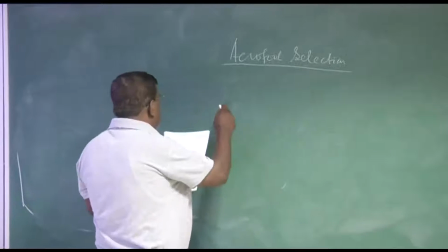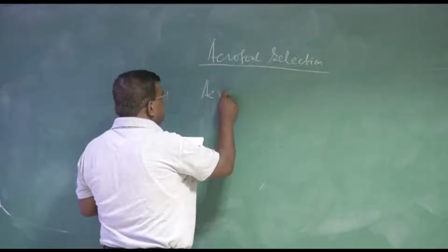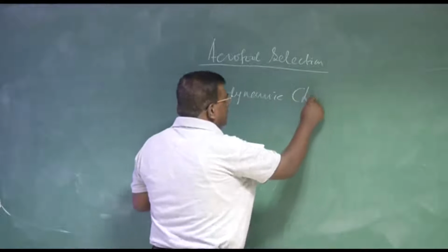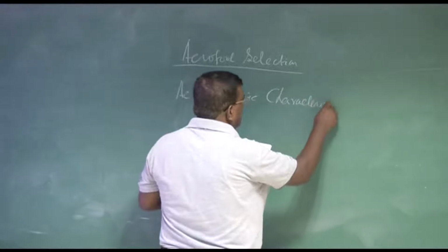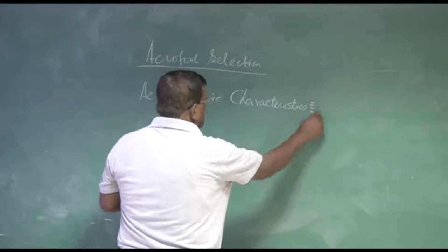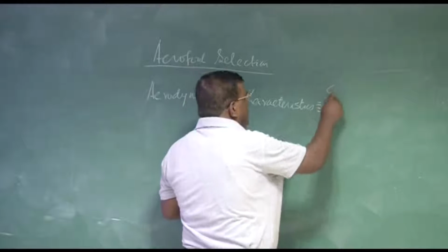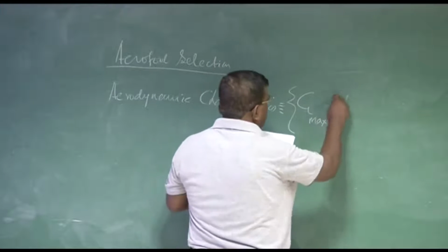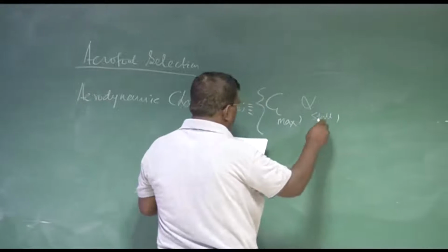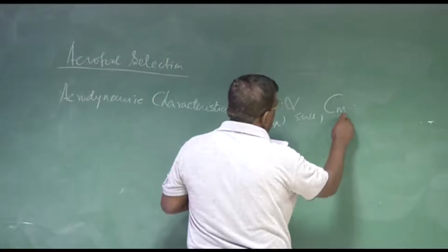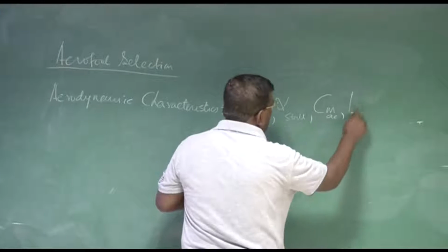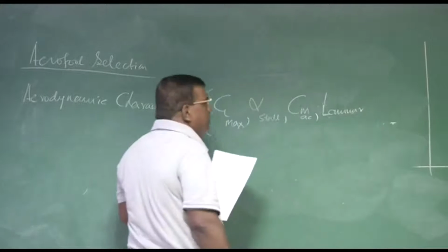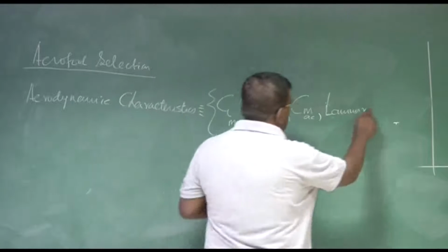And we have seen that especially the aerodynamic characteristics mostly can be covered through knowing what is the CLmax, what is the alpha stall, what is CMAC, maybe whether flow is laminar, you want over most of the part of the wing, etc. Right?